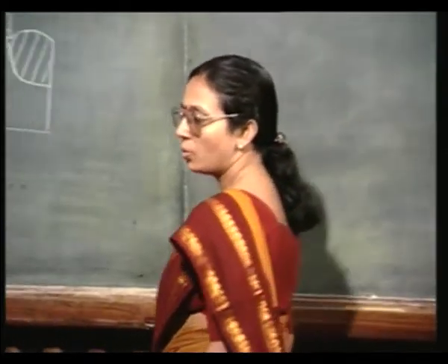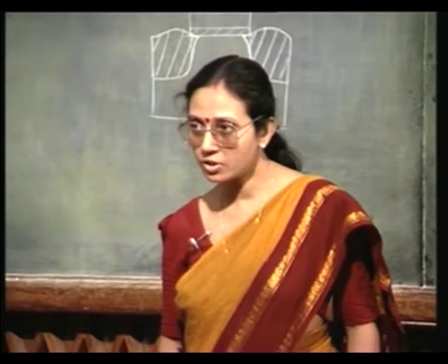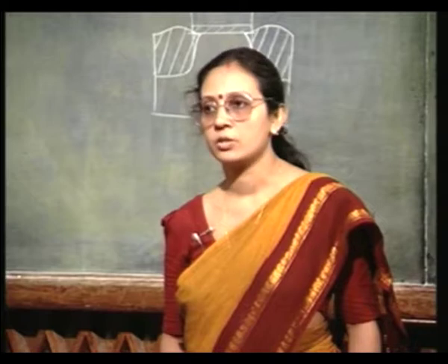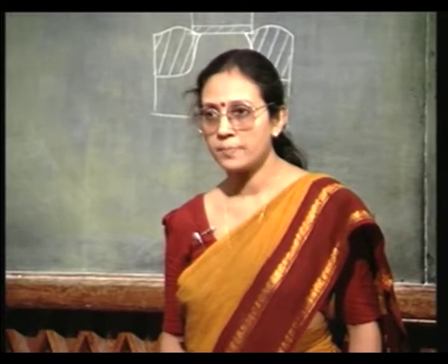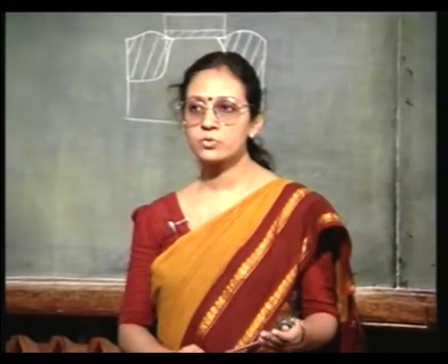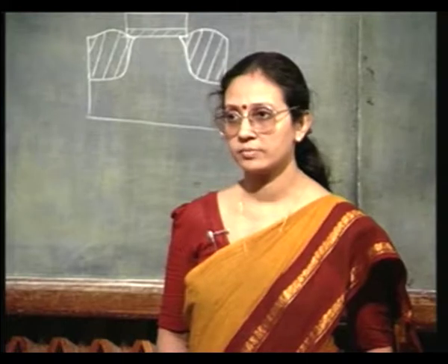So, this is what trench isolation is all about. You cut a trench, you fill the trench, and then you do planarization. Okay. So, this trench isolation is very useful, particularly when we are talking about submicron devices.